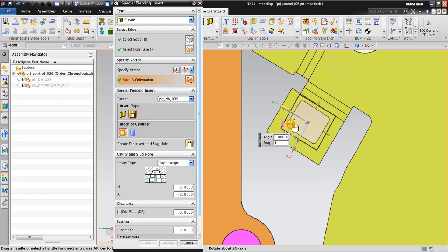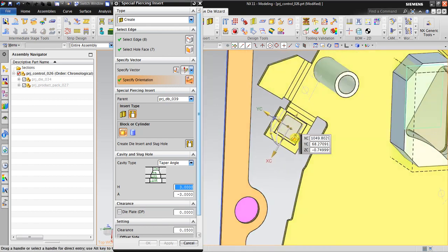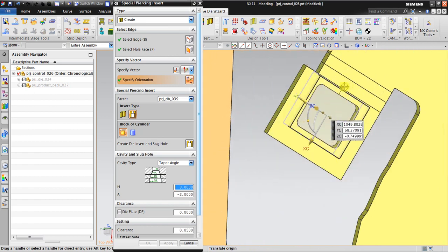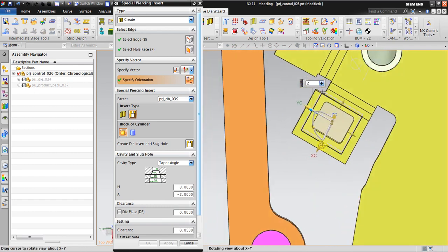Okay. This is good. So if you don't want it too thin like this, you can also increase the bounding box size from the beginning, so you don't need to add the thickness using synchronous technology for all sides.